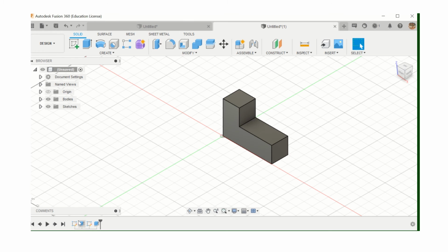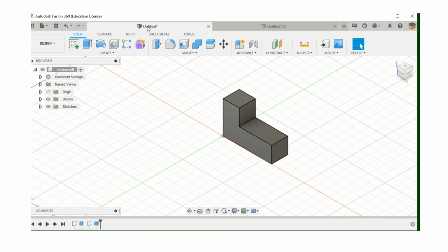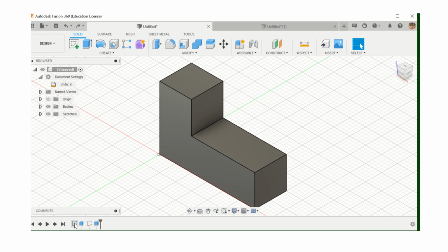and as you hover over it, if you look at the bottom of the screen, if I hover over sketch 1, it shows me what the first sketch is. Then I hover over that and it shows me the first extrusion. Then it shows me what my second sketch was, and then it shows me the second extrusion. If I go to the additive method, there's sketch 1, there's the first extrusion, there's sketch 2, and there's your second extrusion on that. You could also do this.